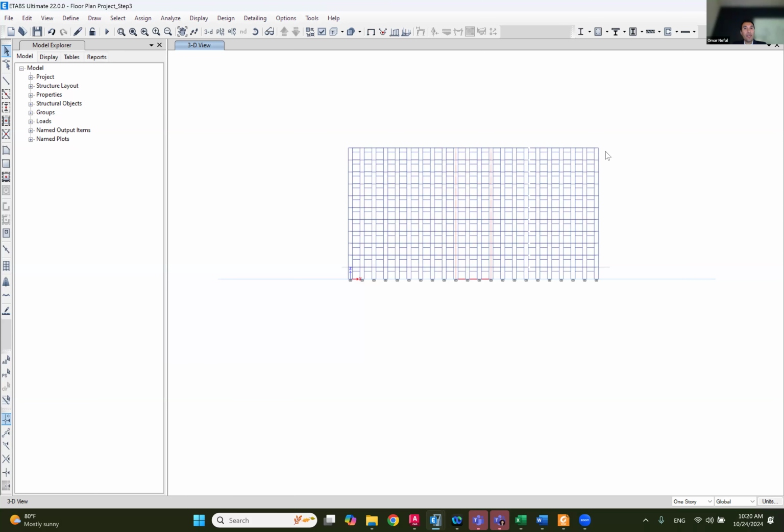So in 11, you can select all the columns here and define new column section and assign the new column section. So what I would do before I start the model, I define all the column sections that I have. I define the 5 section, the 150, the 130, the 100, the 175, the 50, all of them. I make them ready and assign them right away.